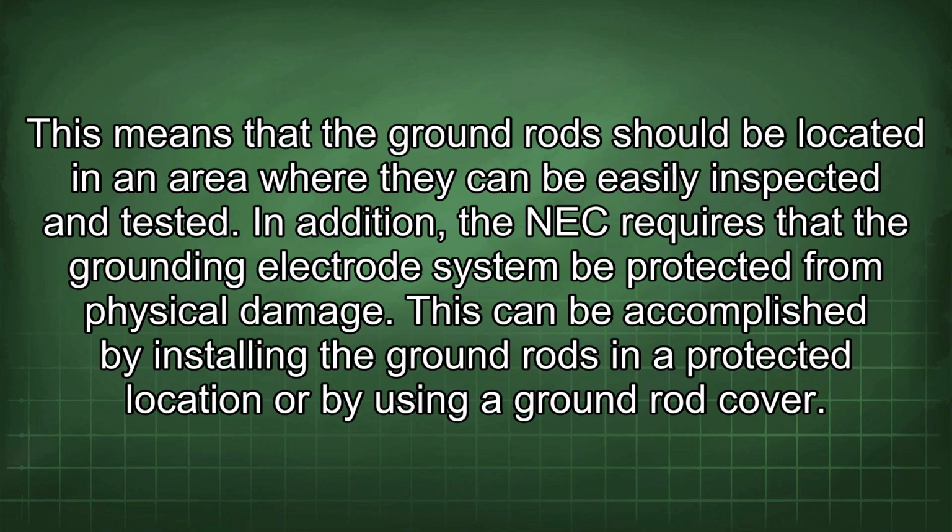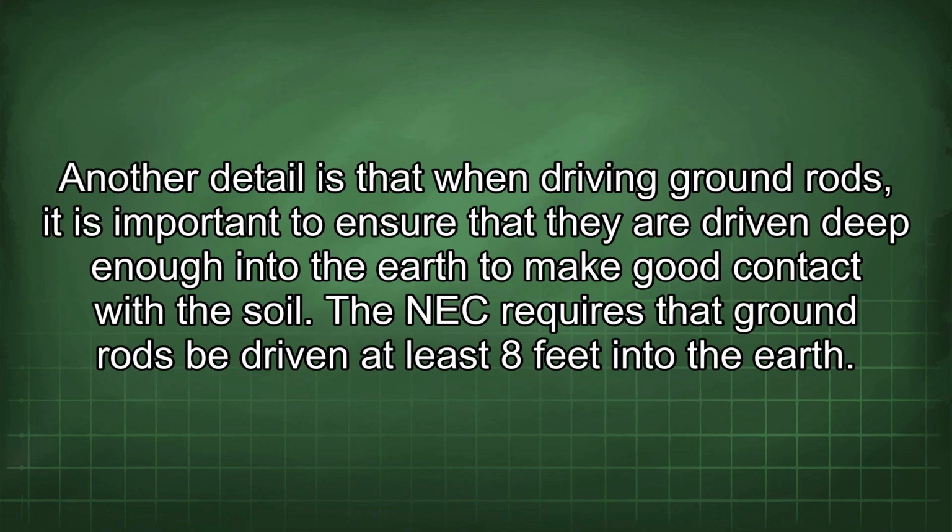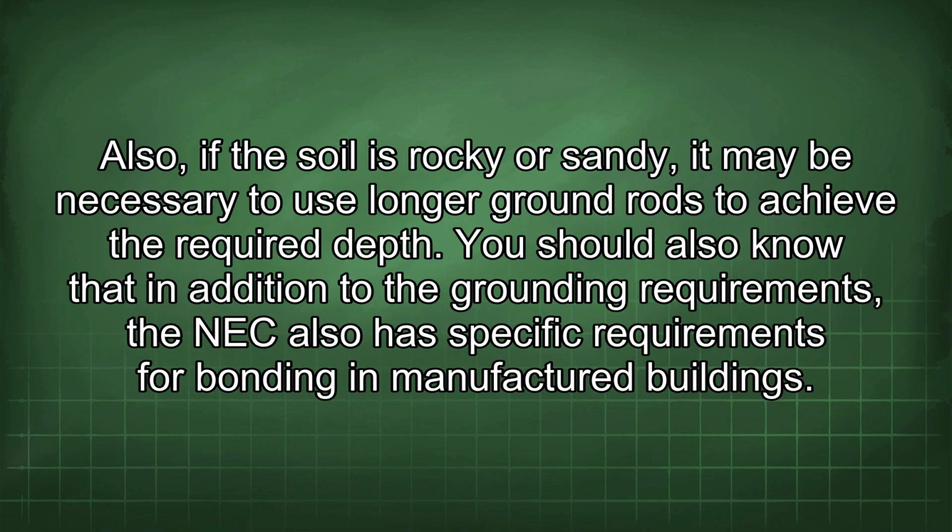In addition, the NEC requires that the grounding electrode system be protected from physical damage. This can be accomplished by installing the ground rods in a protected location or by using a ground rod cover. Another detail is that when driving ground rods, it is important to ensure that they are driven deep enough into the earth to make good contact with the soil. The NEC requires that ground rods be driven at least 8 feet into the earth. Also, if the soil is rocky or sandy, it may be necessary to use longer ground rods to achieve the required depth.